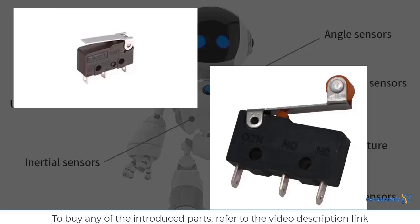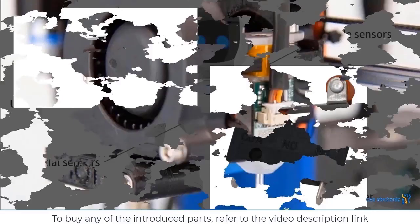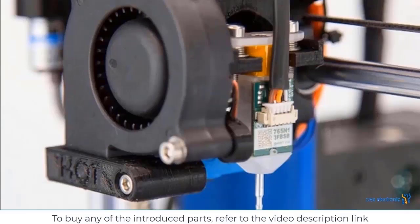For example, the controller, which is usually a microcontroller IC, is defined to hold the arm in place by receiving the microswitch signal. So when the microswitch is pressed by the arm, indicating that the arm has reached its destination, the motor stops and the arm stays in place. And here, you can also see the image of the types of microswitches. For example, in 3D printers, microswitches are used to precisely adjust the nozzle position, and the printer's moving tray is used a lot so that the nozzle and the moving tray are exactly at the desired point. For this purpose, microswitches are used, which are also pictured here.